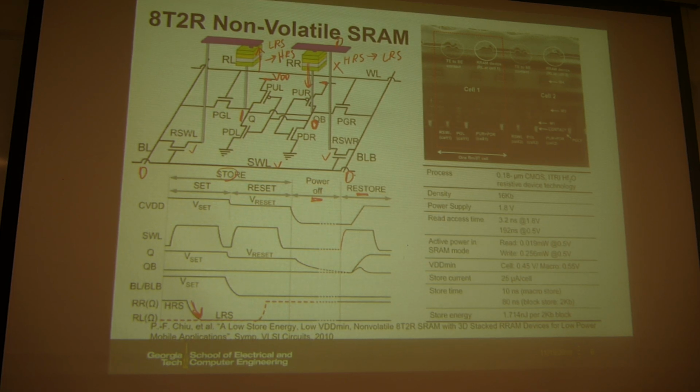So how often do you do this? If you do it once every day, maybe okay, right? But if it's more often than that, then it's not that useful. Every day you press the power button and store to the flash, wait a few seconds, and maybe it's okay. But if you really want to make use of this, then you need to make the endurance of the RRAM compatible, even when you just switch the app, on the scale of maybe, I don't know, milliseconds, or even below that.